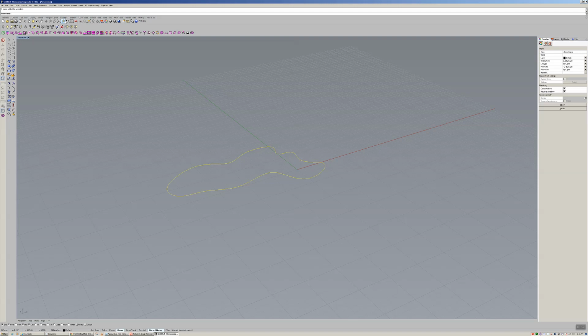This is a very useful command, and it took me probably 10 years to discover what it does and how it helped me with my modeling. As you start modeling, you kind of get lost in space, zooming all around, and you can't see where you're at. When you double left click on that, it brings it right into the center, and you're able to rotate right from the middle of it.